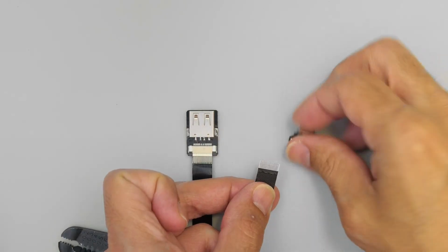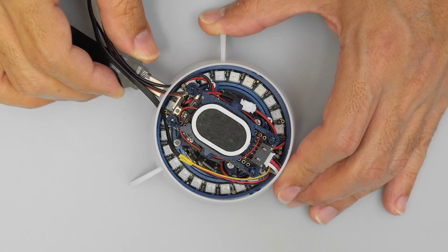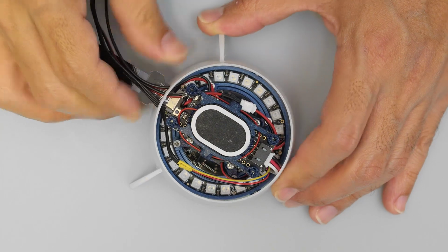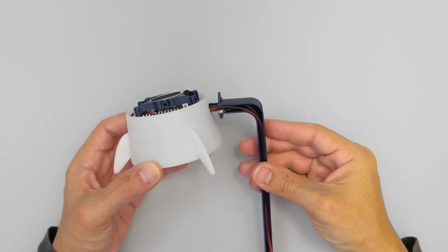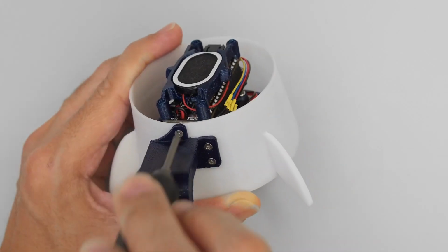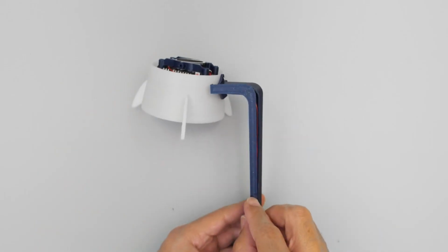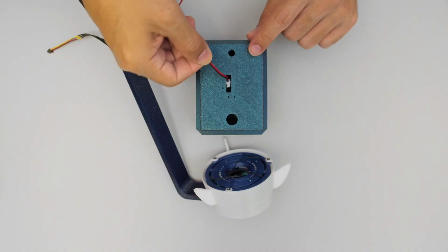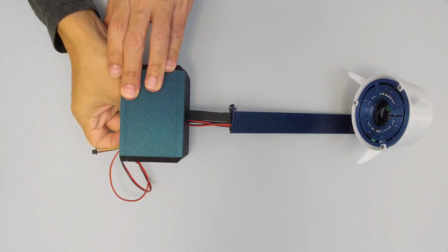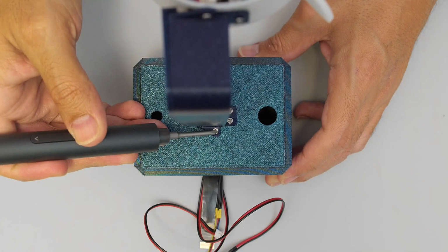A DIY ribbon cable allows the dev board's USB port to be accessible in the control box. The cables are press fitted into a wiring channel built into the rocket's umbilical that gets secured to the side of the rocket. To hide the wires, a separate cover is press fitted over the umbilical stand. Cables can then be routed through the top of the control box with the umbilical stand secured with machine screws.